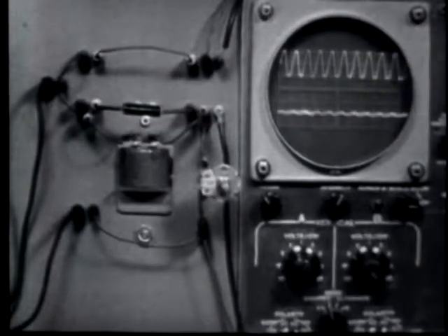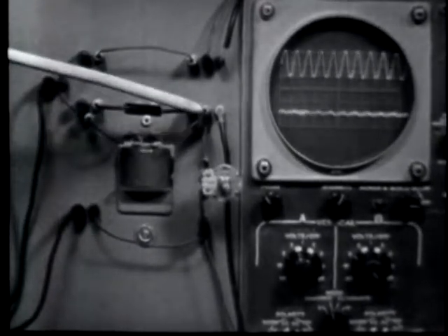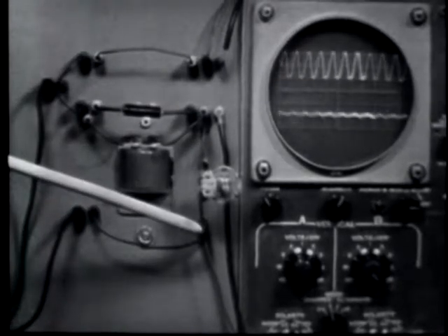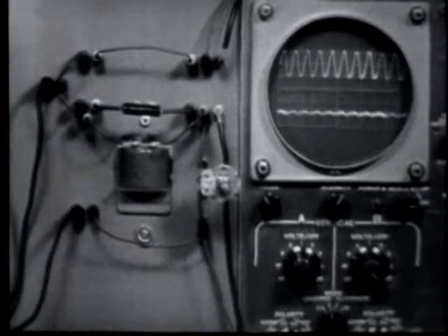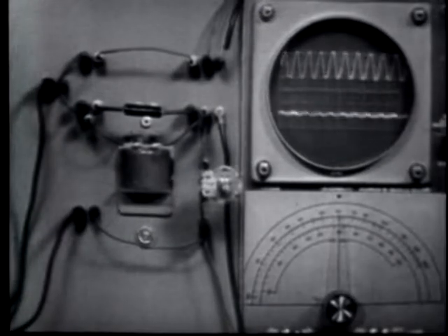Now, as is true of all other filters, reversing the position of the shunt and series components reverses the action of the filter. Let's see. Now, the parallel tank is in the series position. The capacitor here, and across it, or in parallel with it, the inductor. Tank in the series position. In the shunt position, you'll notice that we have our resistor. Now let's check the frequency response of this circuit.